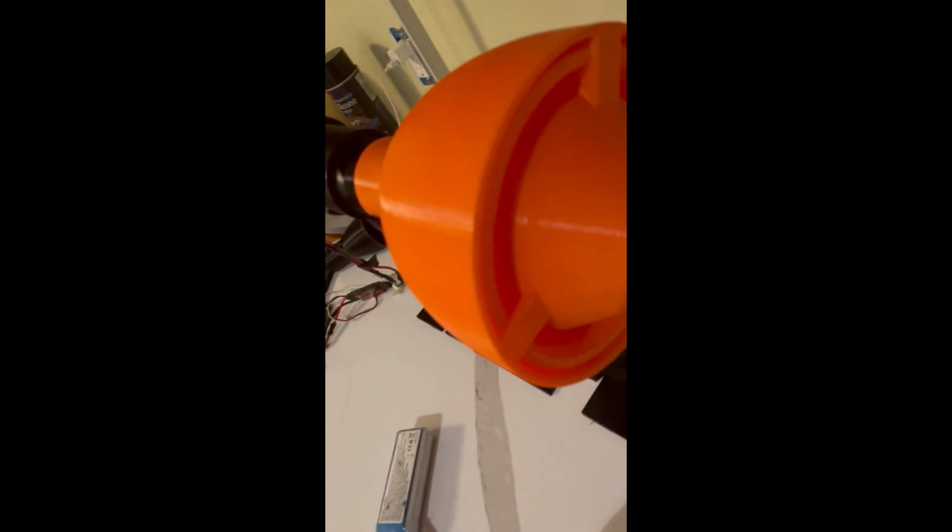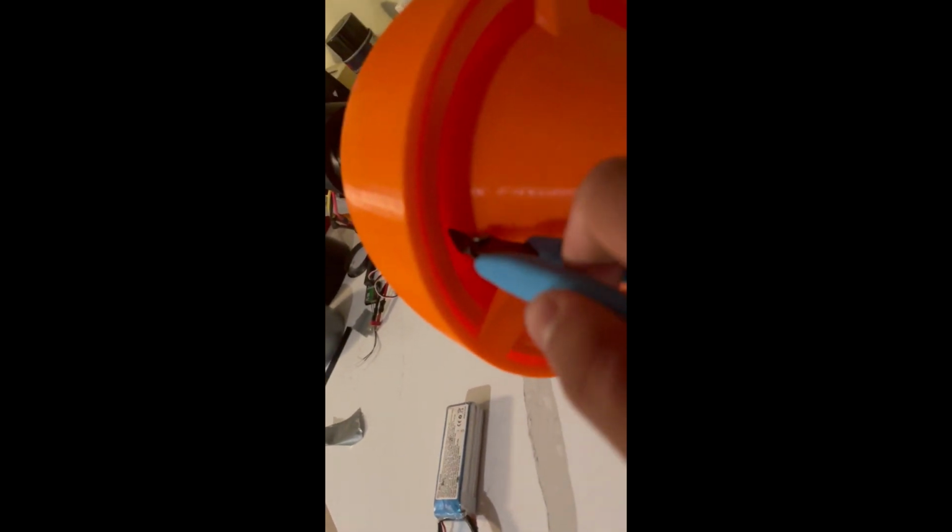So right now, this is the main outflow right here. This is our main outflow. You can see the straws all the way back at the throat, and those straws are there to break up any of the eddies and vortices that are formed by the ducted fan. Because remember, it is a propeller, so it's going to have all that turbulent flow that we don't really want in this test. So remember, this is our main outflow.